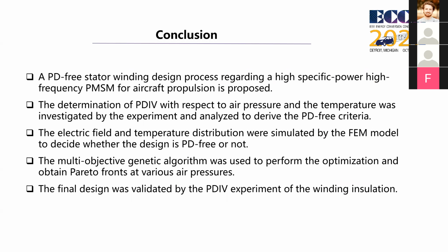Finally, we can draw the conclusion that the insulation design of stator winding is proposed regarding the requirement of PD-free and high specific power. The experimental results and the simulation results are combined to derive the PD-free criterion. And the optimization and the final design is verified through PDIV experiment.